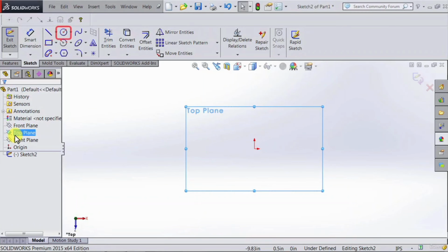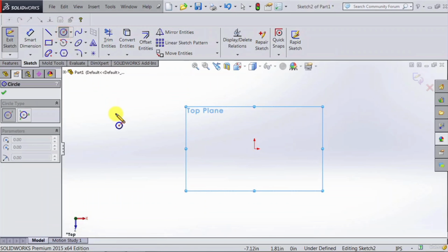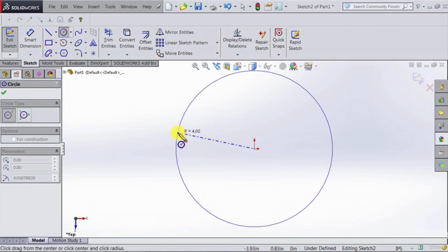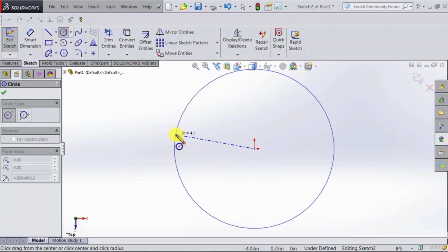Let's start with drawing a standard circle. So we click on the circle icons here. Notice the shape of the cursor has changed. Also, notice the visual representation in the cursor. It actually tells you the clicks needed to draw the circle. A click on the center of the circle, this time we're going to choose the origin, and a click at the perimeter of the circle.